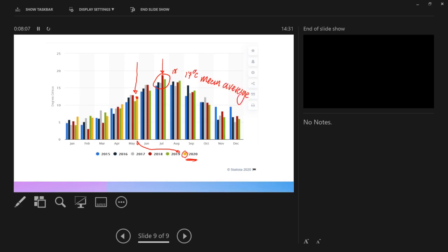in June, okay, well, in our example, we said delta T of 2 degrees. So we said inside the house 20 degrees, outside 18. So heat was going to travel to the cooler point. And we said that it's £4 an hour, or however many chicken wings you can buy at Nando's an hour. But what you need to realise is that we can take extremes here where it's averaging around 5 degrees and it'll be 20 degrees in your house. So that's delta T 15. If we run the figures on that, it'd be absolutely horrendous, wouldn't it?